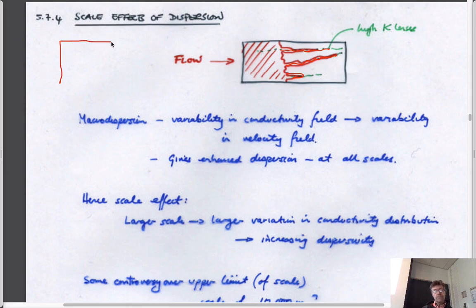If you look at, it's actually based on ideas of fractals, but so the idea is that if you look at an aquifer, and if you look at the heterogeneity that you might have in that, the really big features that have really high velocities on them would be things like faults, where you've had fracturing and displacement that now have very high permeabilities. And these faults would be of large scale and have high permeabilities.